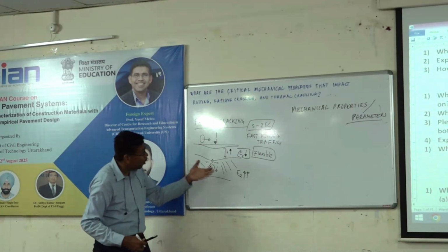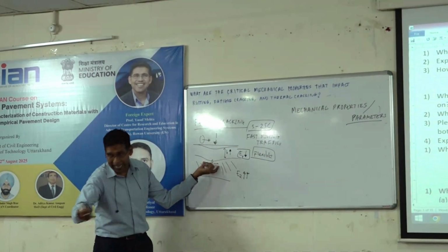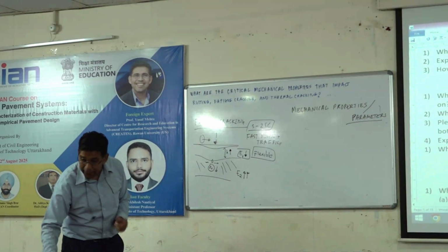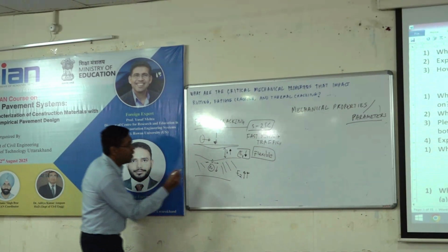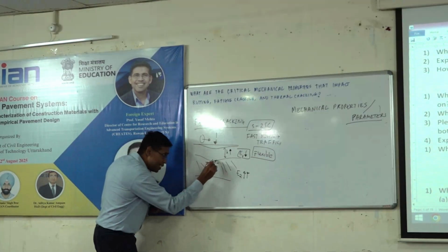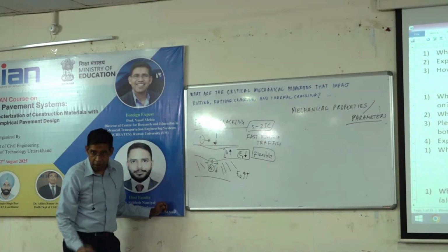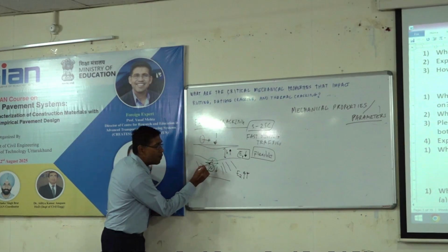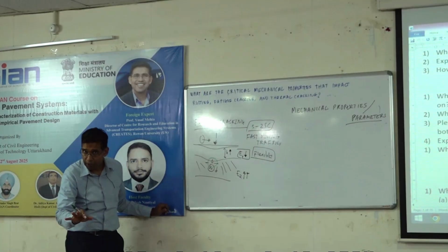That's the thing about pumping. In pumping, remember the water takes the soil away, and now this is almost in air. It's going to accelerate failure and cause cracks. Does that make sense? Everybody with me so far? I'm going to cover this a little bit tomorrow, but I want you to completely understand this. In fatigue cracking, this is a critical mechanical response. If I can minimize this, I will minimize fatigue cracking. Everybody with me so far?